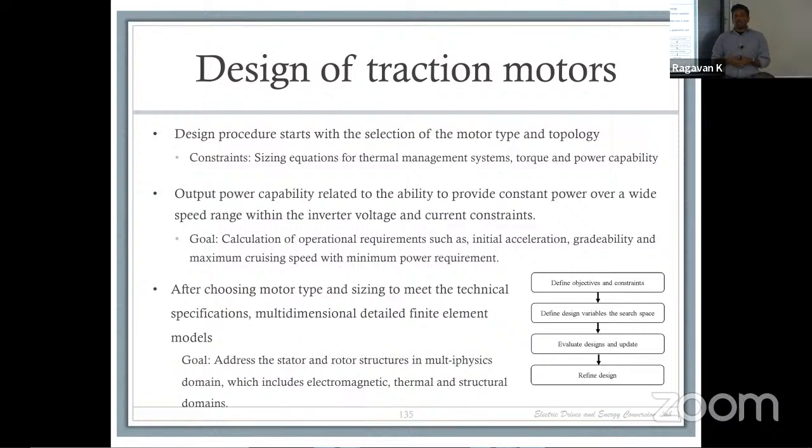If you think about what a hybrid electric vehicle does, when you go on the highway, your engine is basically cruising, or even a regular car. On the highway, your engine essentially is cruising. There is no change to your speed. You're not requiring a high torque at that point. The high torque regions are during startup, right? That's when you need the high torque. So by being able to go to much higher speeds, you can possibly make the motor much smaller.